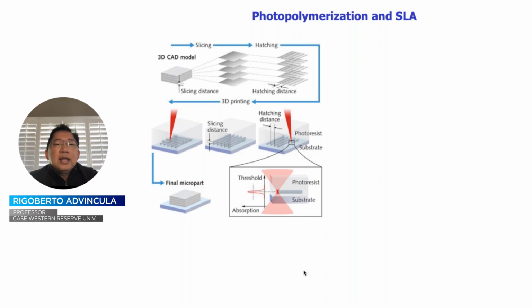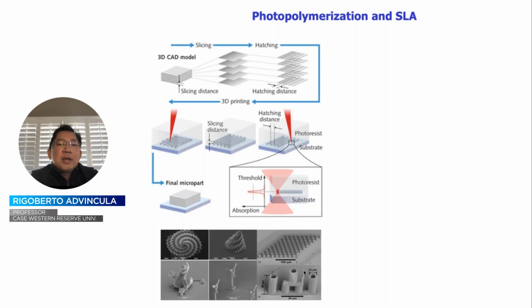So for short, one can use 3D printing in order to extend this two-dimensional patterning into a three-dimensional pattern. And we can distinguish later between a DLP and an SLA. The main difference is that of light projection versus the mechanical movement of, let's say, a laser projected light, where the polymerization takes place at the focal point, or there is a region, and we sometimes call this the box cell, where you have the intense amount of light or directed light where the photopolymerization can be localized. Hence, in combination with a CNC type of movement, or computer numerically controlled movement, one can extend this together with a projection or elevator into a three-dimensional part.